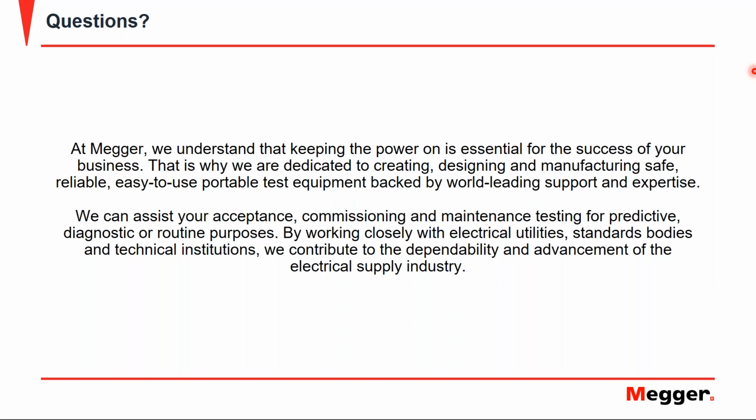So it's only how to perform a measurement, where to pay attention to, how to perform a calibration, how PD pulses look like, etc. So the 5 picocoulomb is not mentioned in the IEC 60270. No, that's purely in the cable standard itself, or in the component standards for type testing or routine testing on those cable drums.